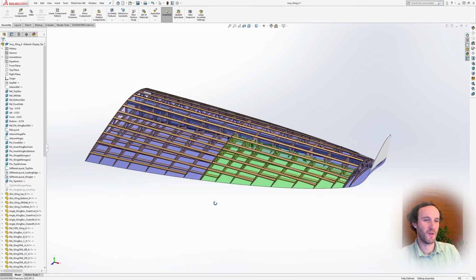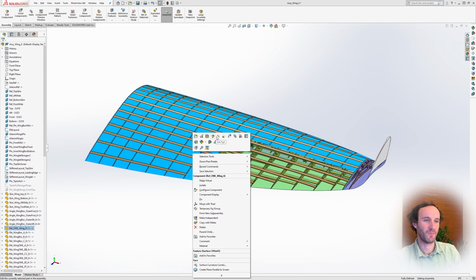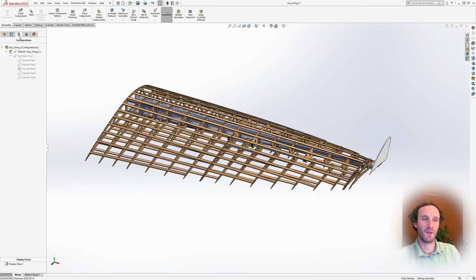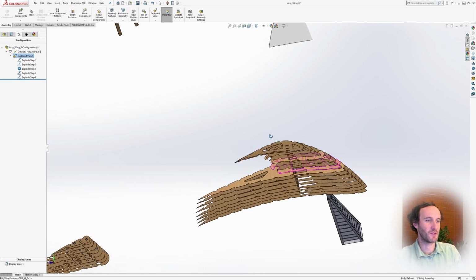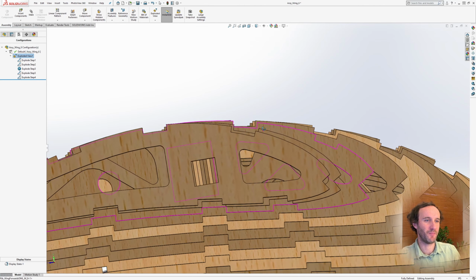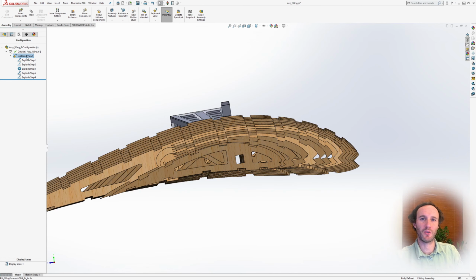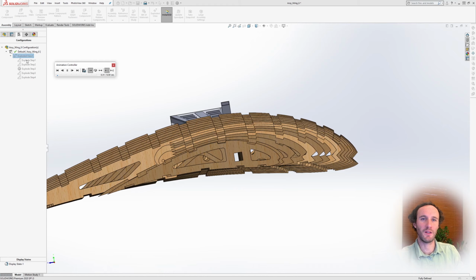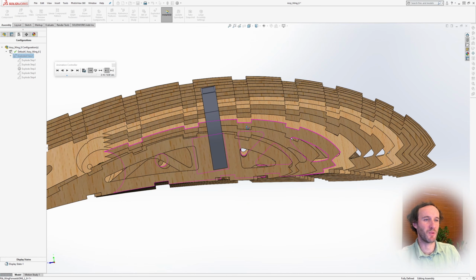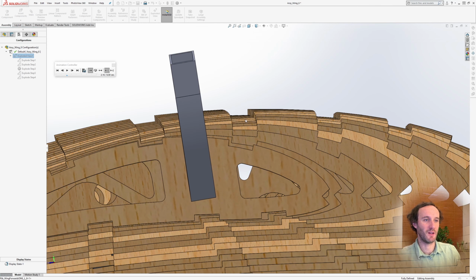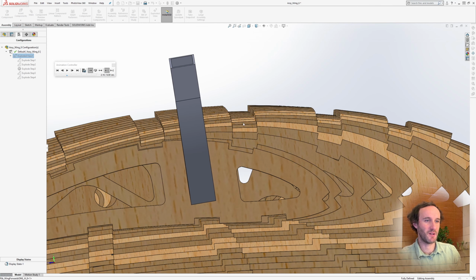Now, during the physical assembly of this wing, what's going to determine the shape and location of the stringers is these cutouts in the ribs. So we're going to lay the stringers into these cutouts. The initial shape of the stringers is straight, and then we flex them into these cutouts, and that determines their shape at the end, the twist and bending.